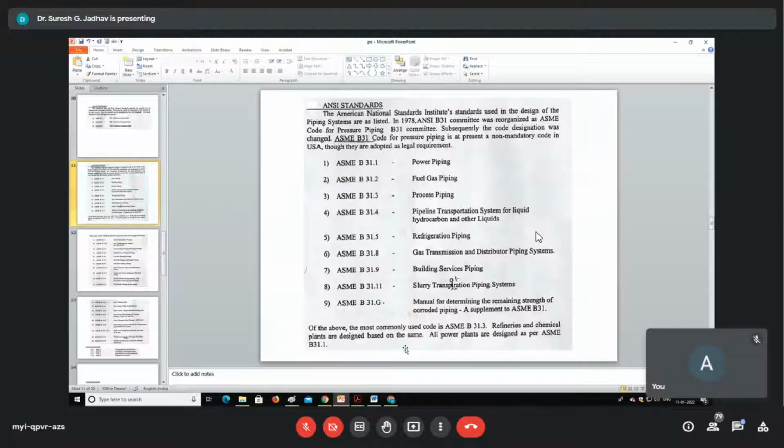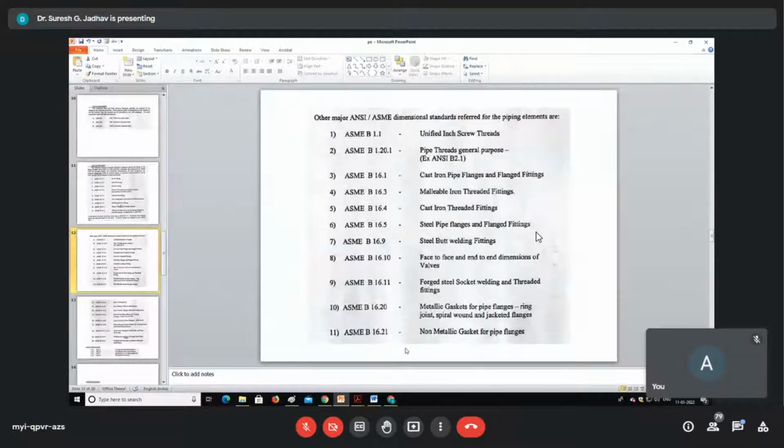Means here we can use power piping as well as process piping. So sometimes for some installations of piping components, more than one code section may apply to different parts of the installations in piping engineering. Here the piping engineer, or we call the user, is responsible for imposing requirements supplementary to those of the code, if necessary, to assure safe piping for the proposed installations, where no section of the code specifically covers the proposed installations.